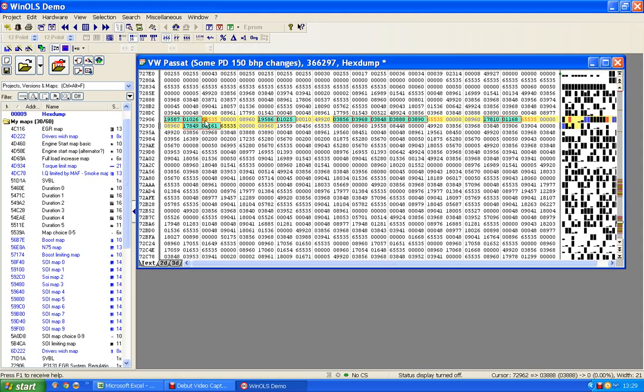But I load it into my car, let's say, and I unplug a connection to the EGR actuator, which will throw up instantly faults about the fact that the line is unplugged. Or maybe I disconnect the vacuum pipe and plug it, or maybe I leave everything alone but I put a blanking plate in the EGR. But there's a whole load of things I could change which might well cause these codes to appear.